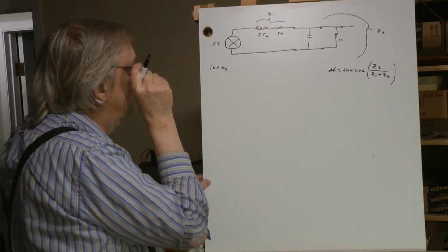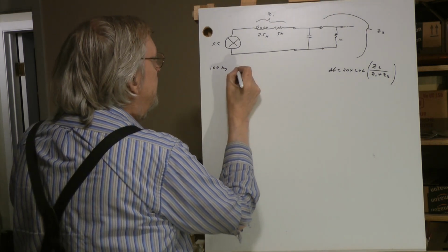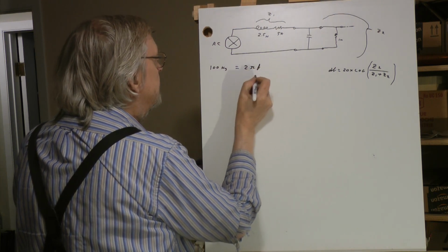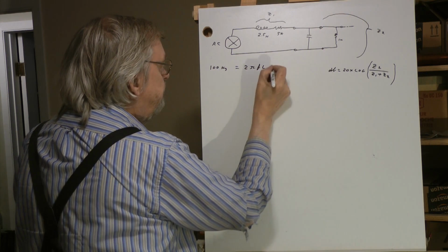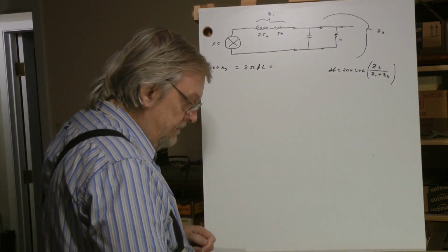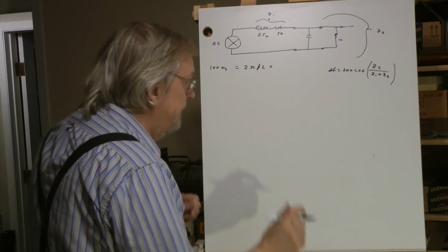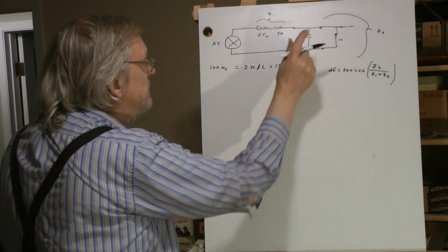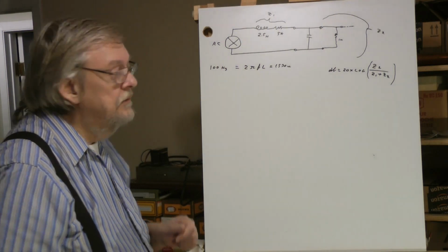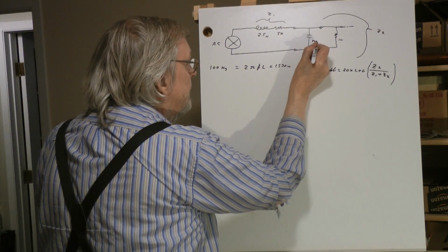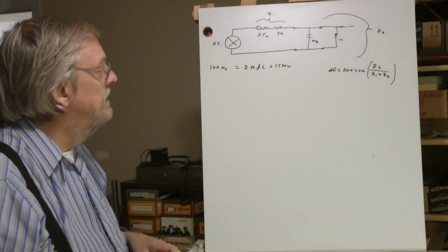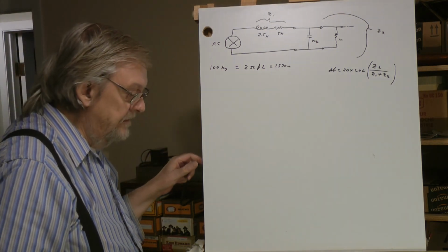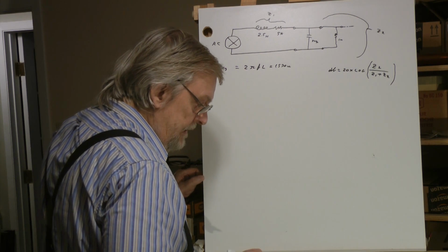This coil has a certain inductive reactance at 100 Hertz. The formula for that is 2 pi times frequency, which is 100, times inductance. Now I didn't want to waste time with the calculator, so I've pre-done everything, and that would be 1570 ohms. Now the capacitor: I measured my 6-foot cable here and I got about 500 picofarads. That's millionth millionth farads, or 500 times 10 to the minus 12. Yeah.